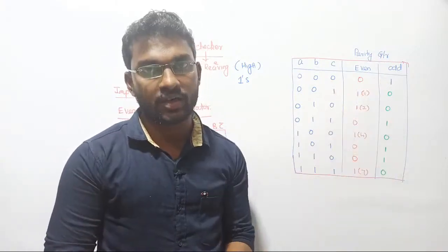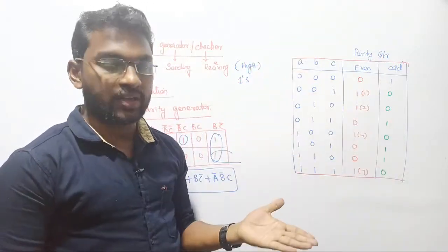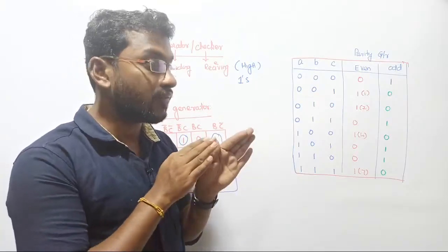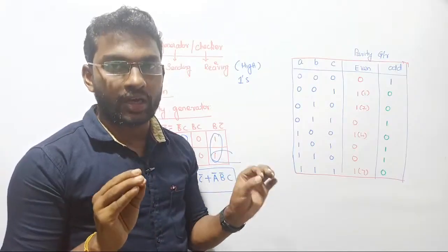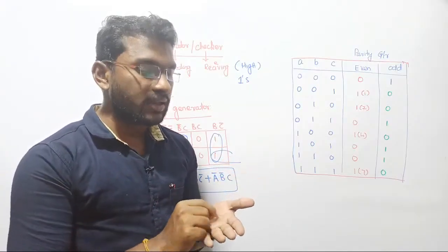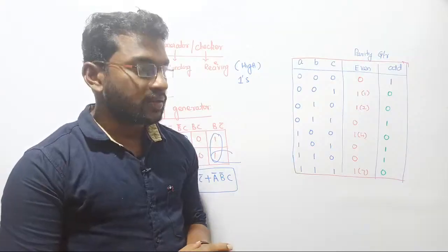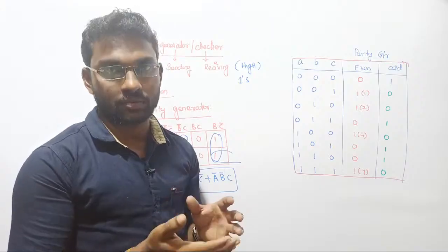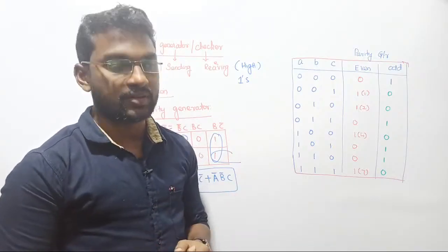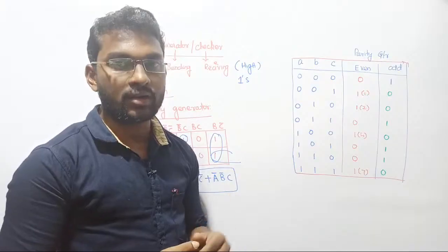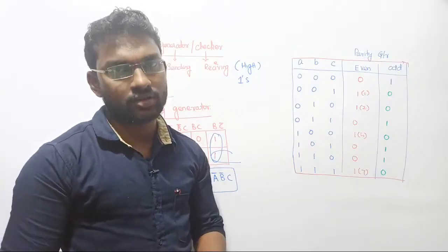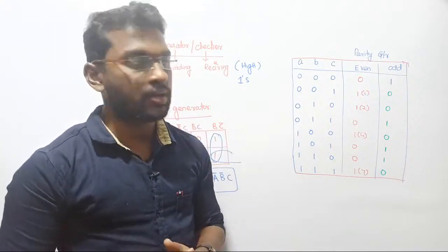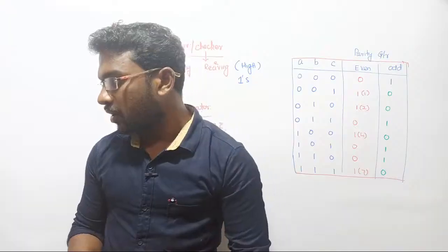This is the odd parity generator. There it will compare all the ones in all messages. If your system is having only an odd number of ones, then there is no error detection, and the system will accept the data since there is no error. Suppose it finds an even number of ones, automatically it will create some message and send it: there is some problem in the system because there was some error, I detected it, just go and check it. Like that some messages will be generated. Clear? That is how your parity generator and parity checker will work. That's all about parity generator and parity checker.